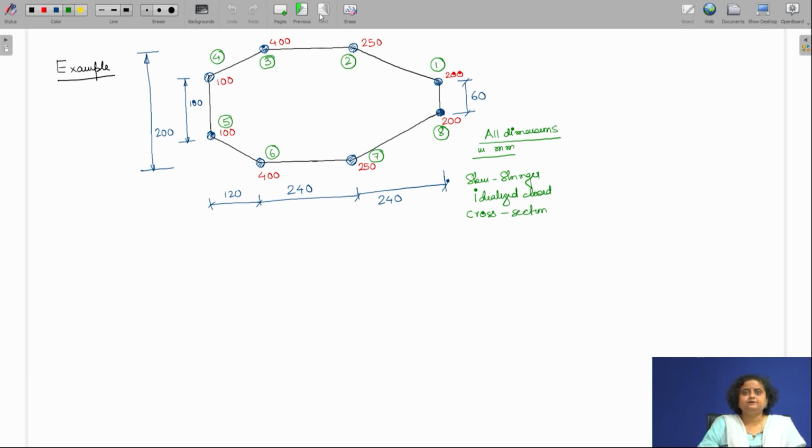And then if the shear force passes through the shear center, we have to use the Bredt-Batho theorem and find out the assumed value Q0. The same process has to be applied in a skin stringer idealized cross section as well.